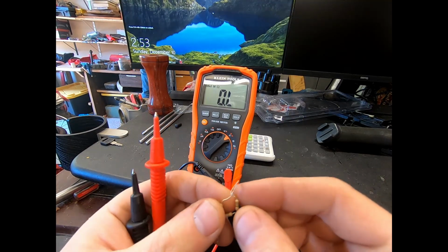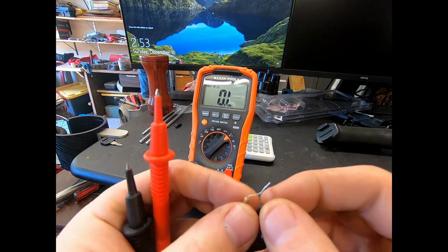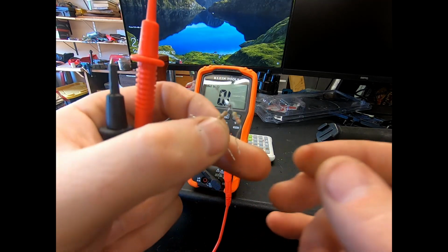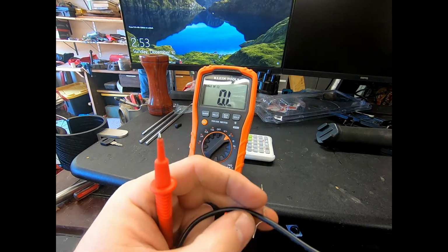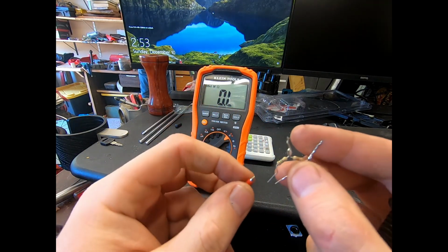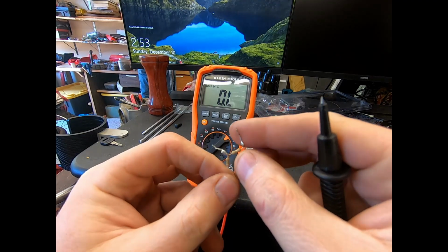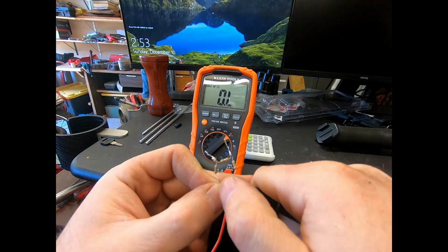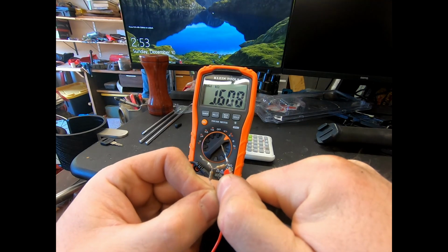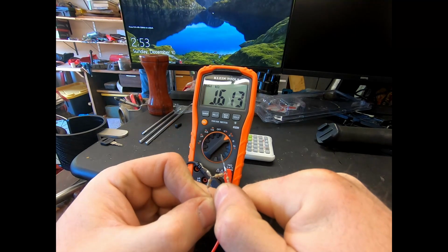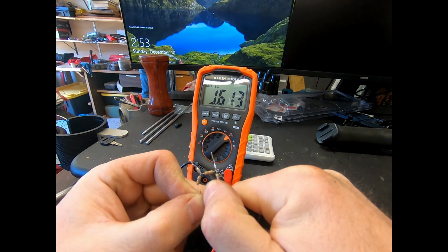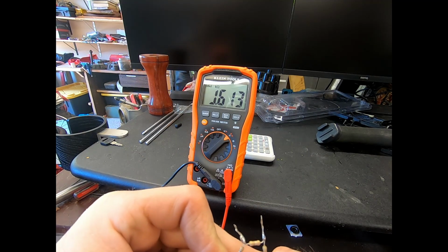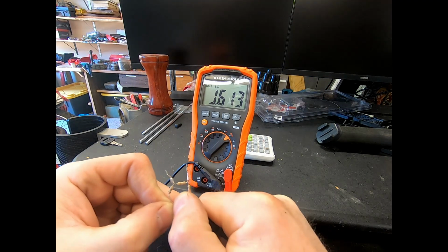We know that we need a 620 ohm resistor to be able to activate the 2-wheel high circuit. I ran through all of the stuff I have in my electrical drawers and ended up putting together a chain of resistors that I think is more than close enough for the task at hand. So we're going to stick that on there and check it, and this should give us, let's say, 613 ohms. That's pretty good. I can live with that. You can see that it's 0.613 on the kilo ohm scale.